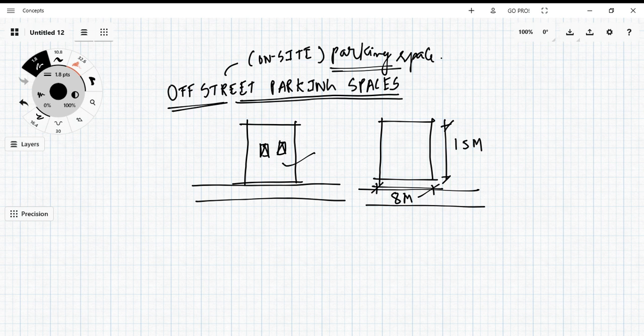As per bylaws, we have to leave setbacks. Every one of you architects and civil engineers knows that we have to leave the mandatory setback space. So what NBC is saying is, irrespective of these open spaces, we have to again provide for the parking area. That means you have to provide the necessary space around it, then only you can have the parking, okay.